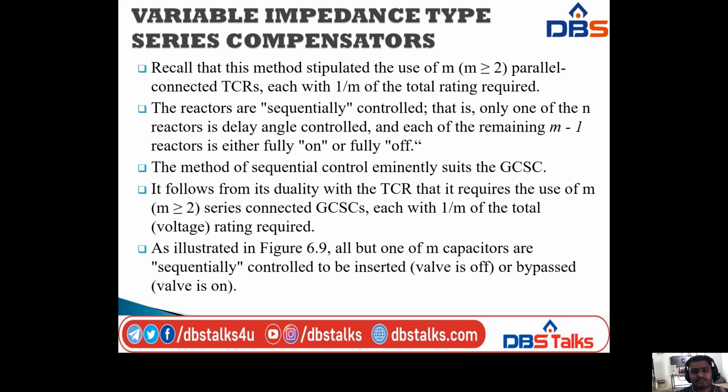So the reactors are sequentially controlled, that is, only one of the m reactors is delay angle controlled, that is for the TCR case, not for the GCSC. Each of the remaining m-1 reactors is either fully on or fully off. So the method of sequential control eminently suits the GCSC also. It follows from its duality with the TCR that it requires the use of m greater than or equal to 2 series connected GCSCs, each with 1/m of the total rating required, that is, the total voltage.